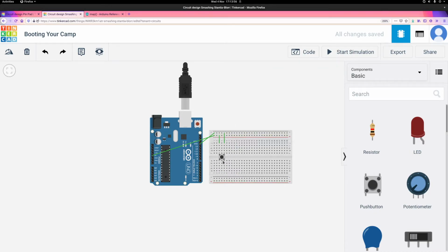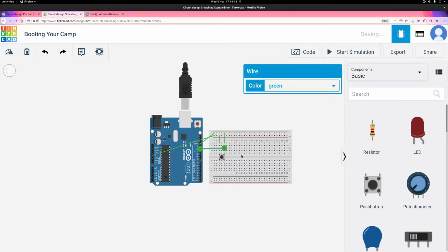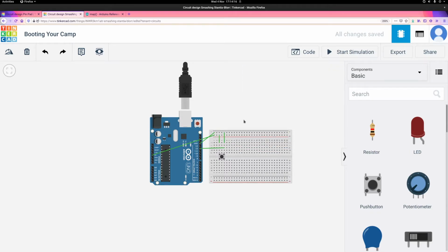And then we can run power through it, and when we press the button, we'll be able to pick that up. Now, to actually read this value, we'll need to be reading the voltage at some place. So we'll be doing that by reading the voltage here, say, at this H value, or H row, column. And we'll connect that up to pin 12, just pretty arbitrarily.